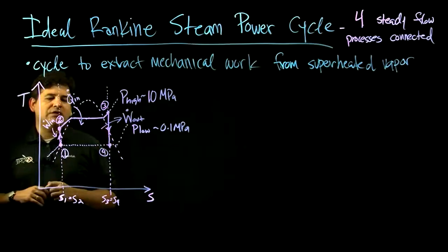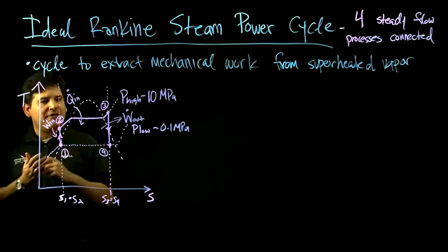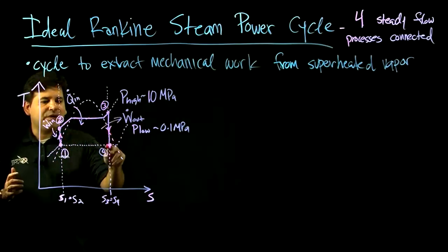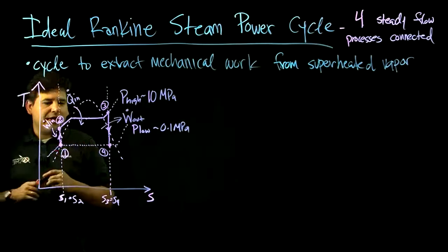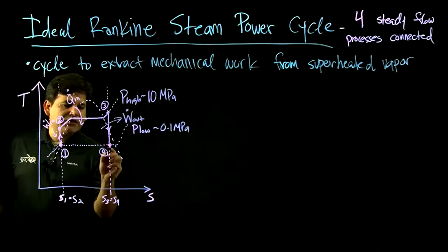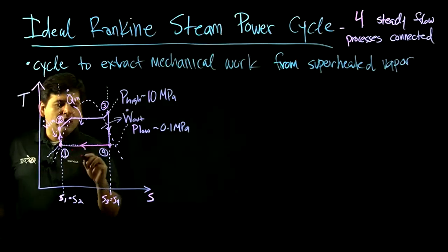If you do that to make it a more compact size, you have to bring this working fluid from these high energy states back to this original state. And to do that, you always have to have in a heat engine some phase of the cycle where there's energy being taken out by heat transfer.